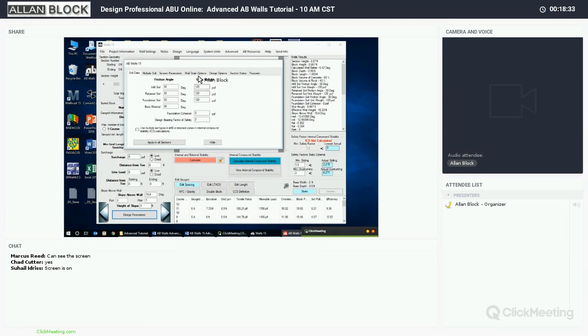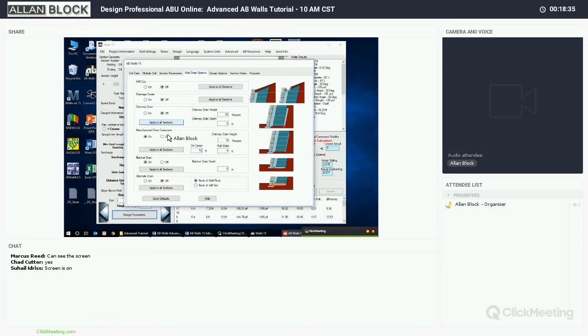So let's go back to the design options again. And the last thing I want to show you, I'm going to turn off the composite and blanket drain, is this alternate drain detail. It's so important to show how the toe drain and heel drains might be vented. Very often that gets overlooked. On commercial sites, maybe a little bit better. They might show where that drain might be vented or taken to some type of a stormwater collection system. But on most options, they're assuming they're going to come through the face of the wall.